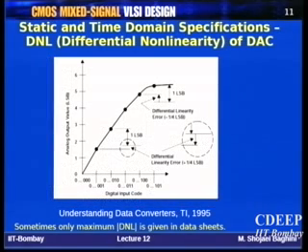Similarly, you can have this for a DAC. The characteristics of DAC and ADC are very similar, so I thought it is good to look at them. If you look at the definitions, usually DAC and ADC are treated together. You just change the X and Y axes, and then you get the DAC characteristics. Your X-axis will be code and the Y-axis will be values.